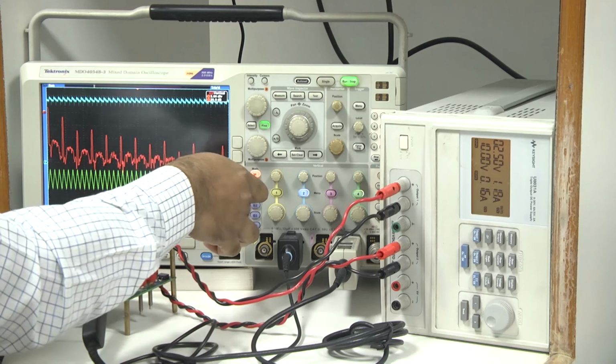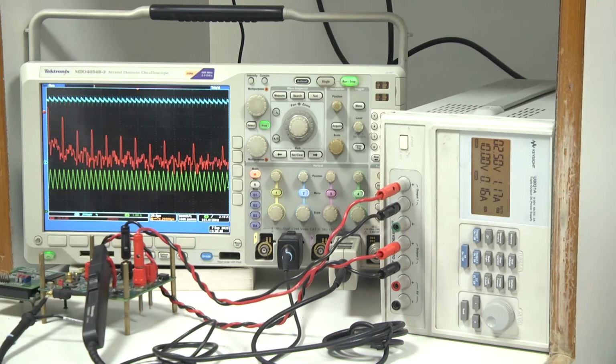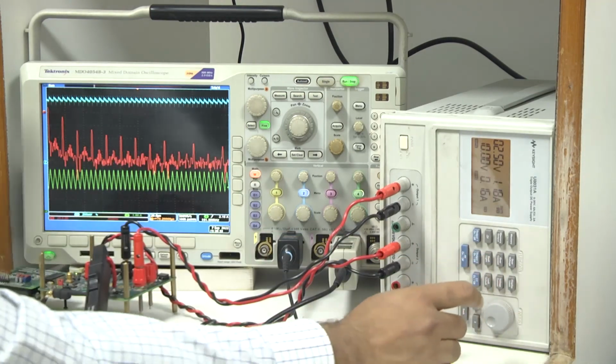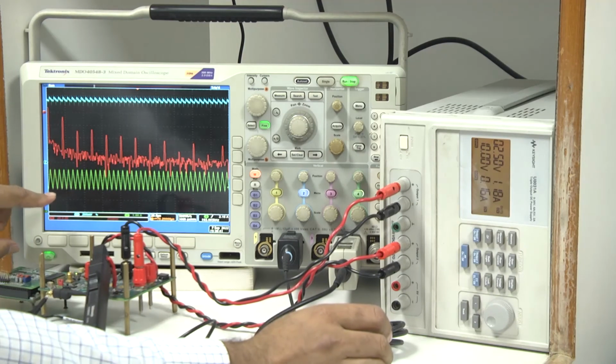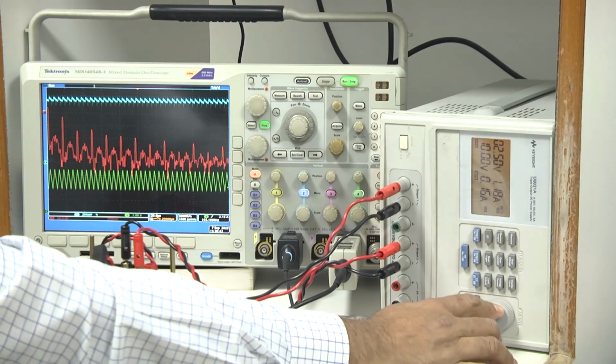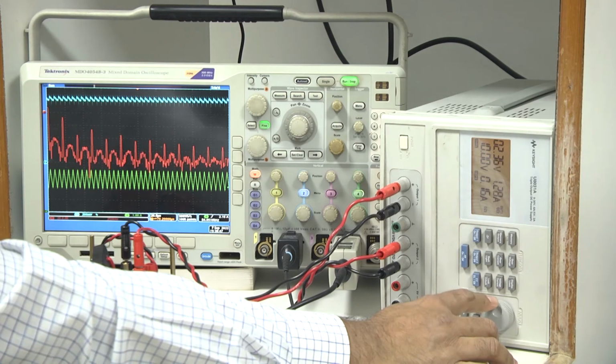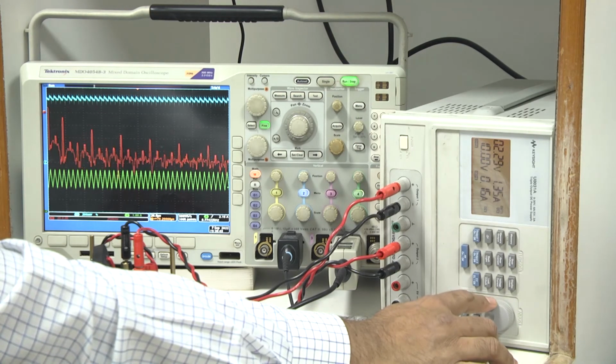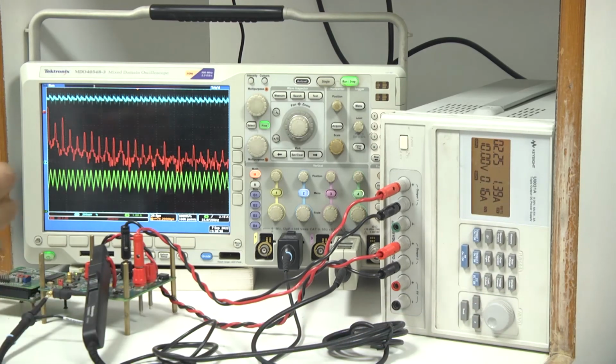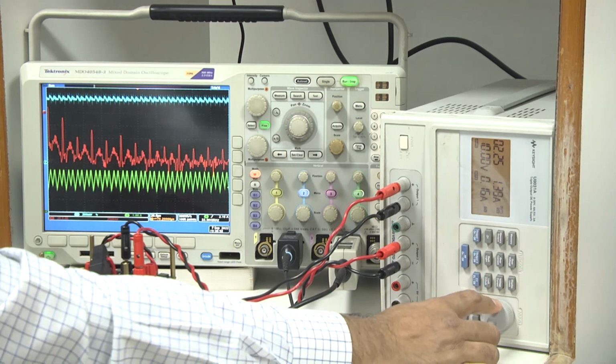Today we have demonstrated that at 2.5 volt the current loop is perfectly stable. Now, we are reducing that to 2.25. So, let us go to 2.25. We are slowly decreasing the input voltage, and at 2.25 it is almost on the verge of instability.